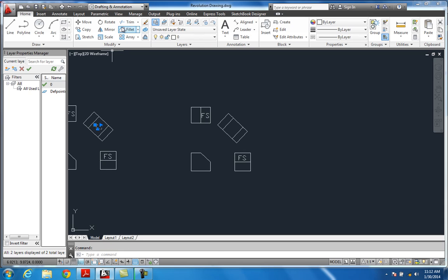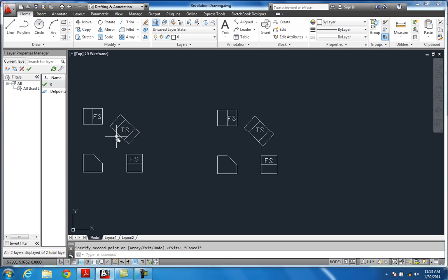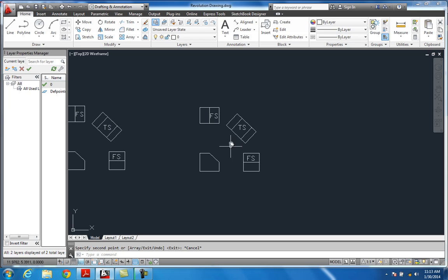And now if we come in here and do a copy, I'm just going to copy and bring that true size over into this box. So this is the same auxiliary, the same way I did the plane auxiliary method over here. This works the same way. You're just taking and making this run flat, and it depends on where the angle's at, how you're going to do it. But that's basically how you revolve it and get that shape.